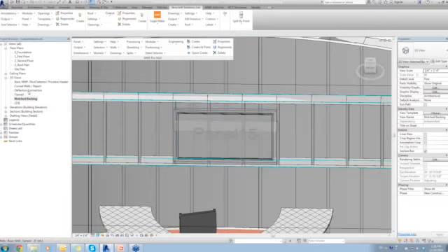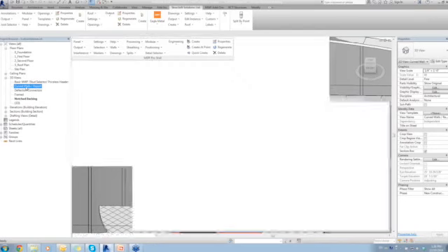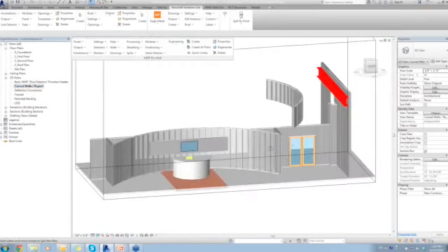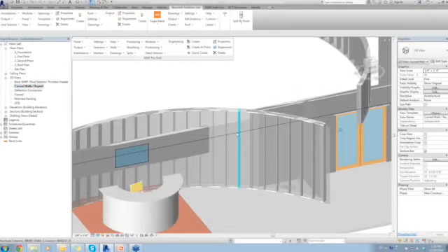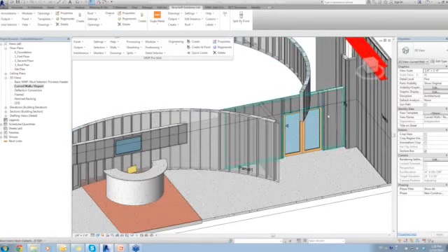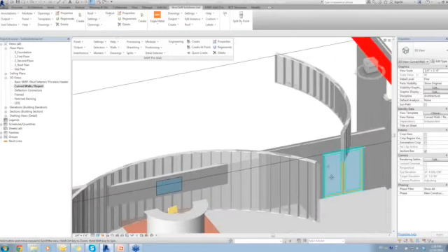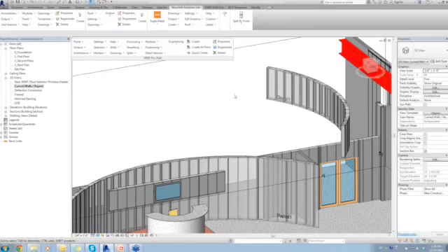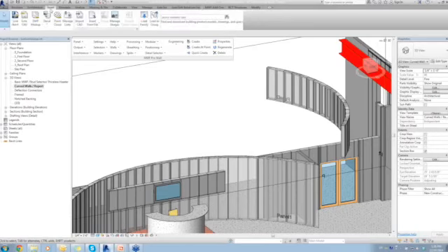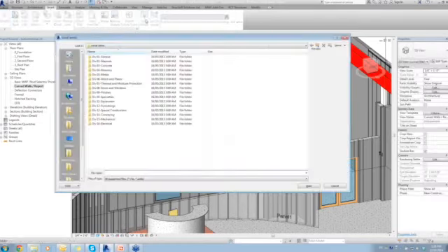So lastly, I'm going to jump to the curved walls we have framed here. You'll notice I have this big one in the front, and I have some of these head of wall or soffit walls up above. First, I want to load in the perfect curve SCAFCO tracks. So just like loading any Revit family, I open the load family command.